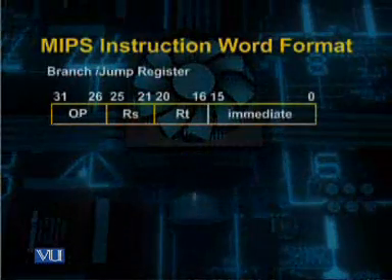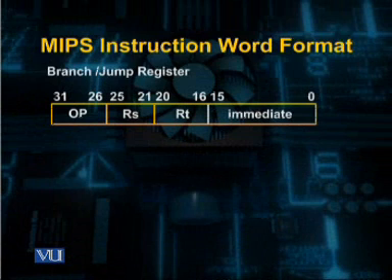However, over here the significance of the immediate value is that it gives us the location where to jump if the condition is met, and the condition is basically tested by using different modes of operations. For example, as you can see over here, it can be used to compare and test.